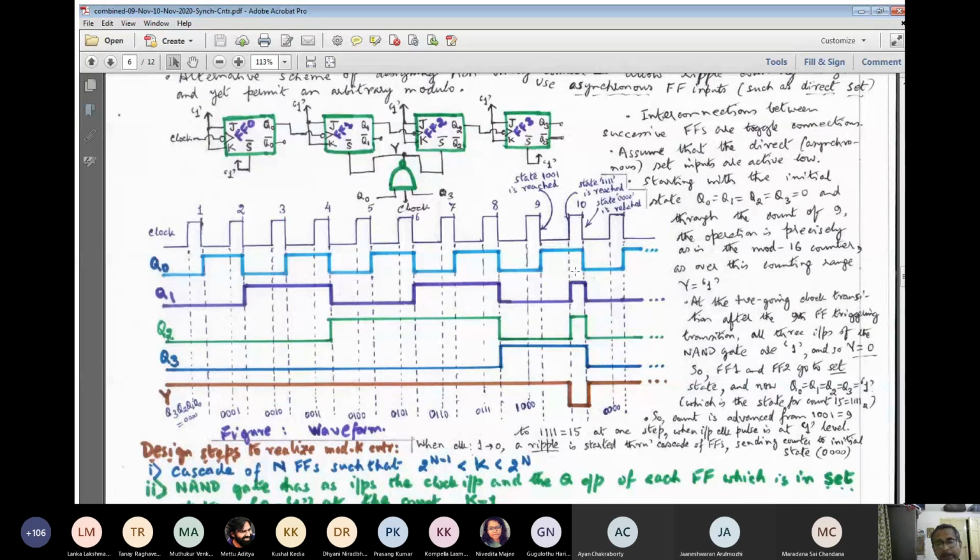For that, the strobing input, that means the decoding logic, has to be enabled after the rising edge of the clock. Okay, some delay will be there, and you can question how the delay will be worked out. For working out the delay, normally we take into account a monostable multivibrator. So after the rising edge event has taken place, through an RC circuit we can generate a delay, taking 10 nanosecond delay for two successive NAND gates, of 20 nanosecond. After that you generate the strobing pulse, the strobing input.